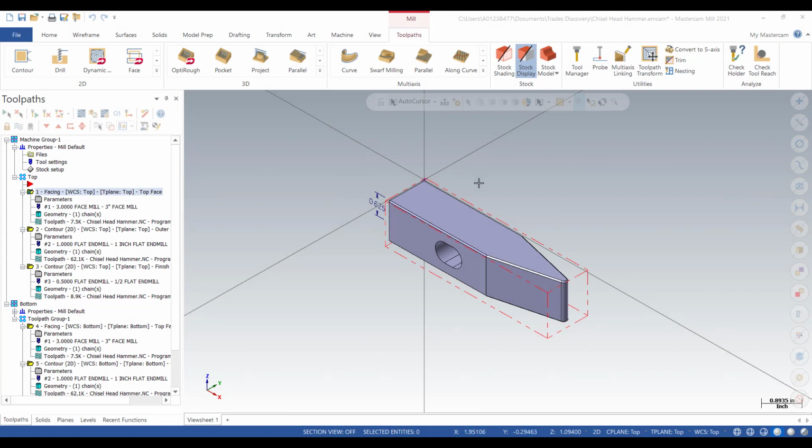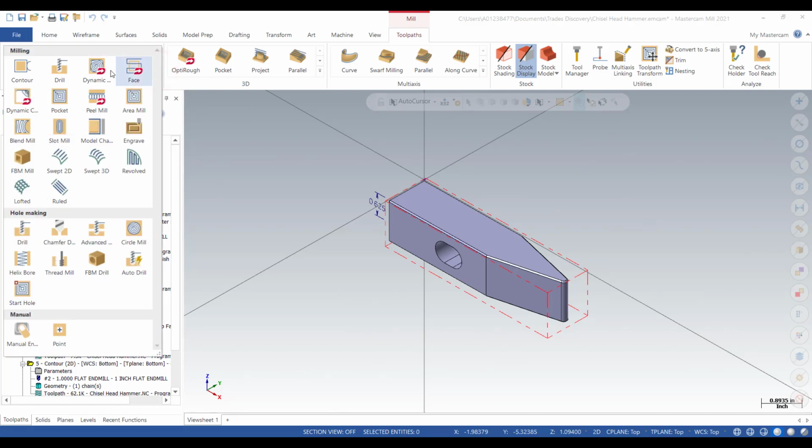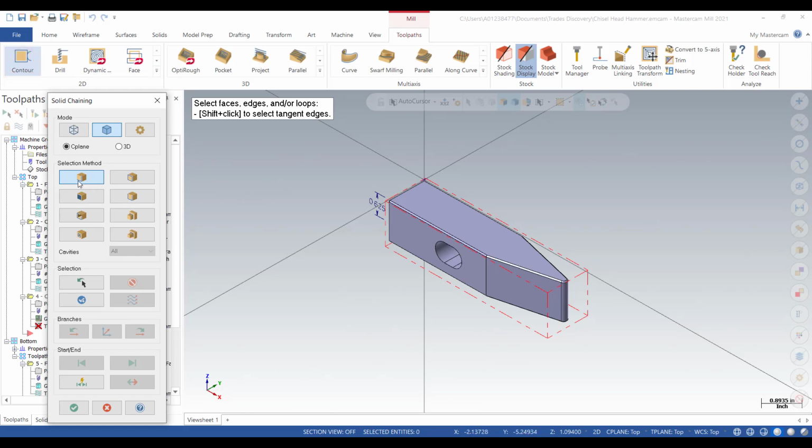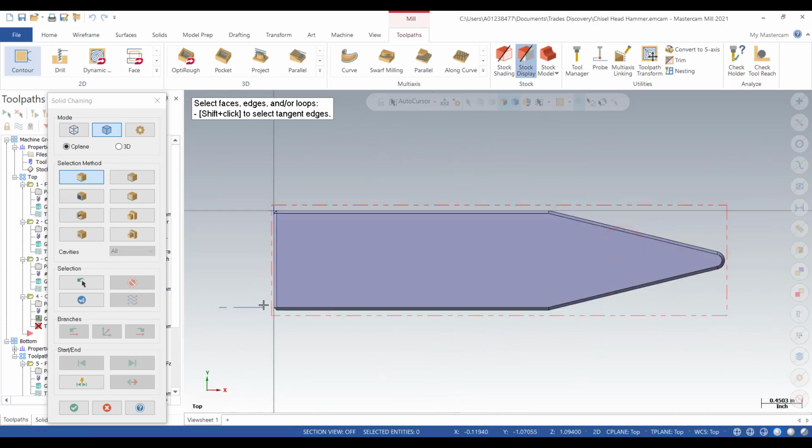Another toolpath we're going to practice is the chamfer toolpath to create that chamfer around on the top and on the bottom. We are going to add that toolpath here in the top. So you see where the arrow is, we can move that arrow up or down with these arrow buttons here. So if I press that, it will go down. So we're going to add after toolpath number 3 right here. So once here, we'll go in the toolpath selection and pick contour again. We're gonna basically be picking the same contour we did before. Same principle, so the green arrow should be going clockwise.